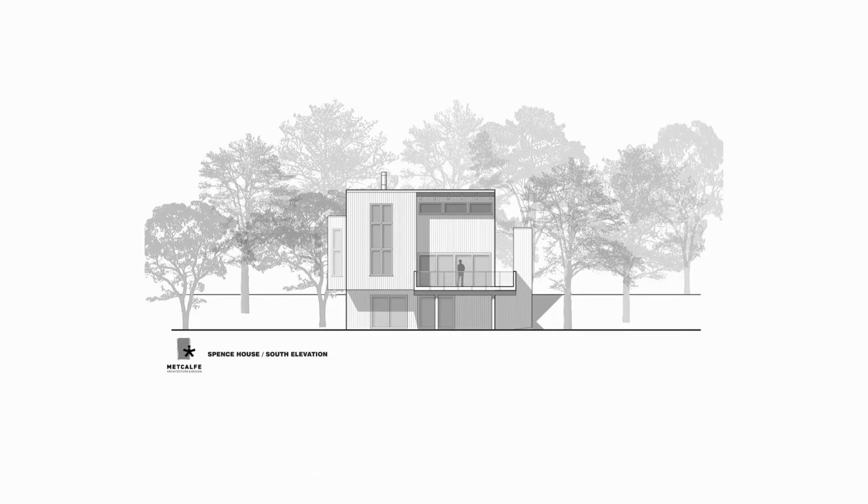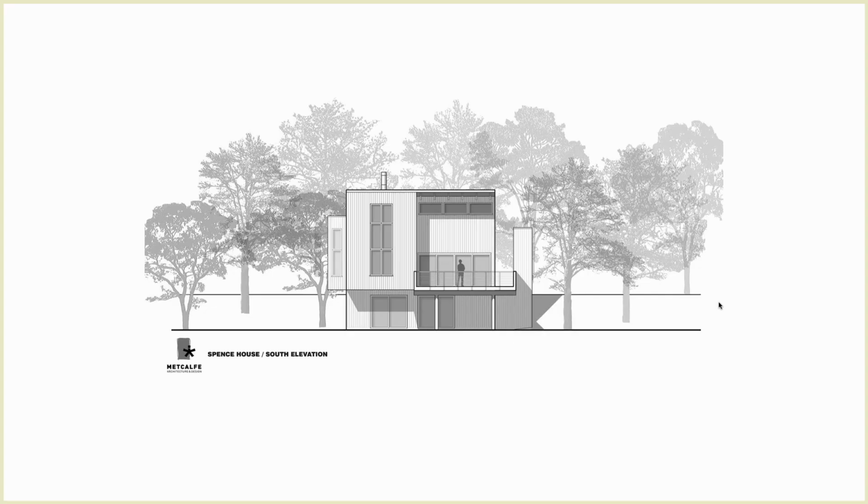And again, line weights here are critical. So we can really easily distinguish what's coming toward us, what's thickest, what's thinnest, based on just the line weight. It helps to have a little bit of shadow here. The shadows are definitely helping, I'll admit that. But if we look at the line weights, our thickest line is right here at the deck. Goes right around there. That's our thickest line because that's popping out toward us. Our next thickest would be this edge of the building coming around like that. Then we'd go to this, would be number 3. That would be number 4 from an outline standpoint.